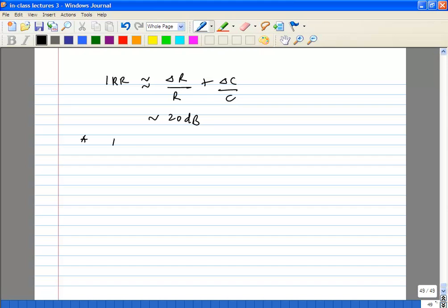What else can you have? You can have issues because the 90-degree block is going to add noise, and it can cause linearity problems. The RCCR won't have linearity problems because it's a passive circuit, but it will definitely have noise issues. Of course, there's going to be a power issue, because CMOS circuits don't like to drive resistive loads. You need lots of power to drive resistive loads. So if you're going to drive an RCCR network, at least on one side you are driving a resistive load, resistive and capacitive, but at some frequencies it is resistive.